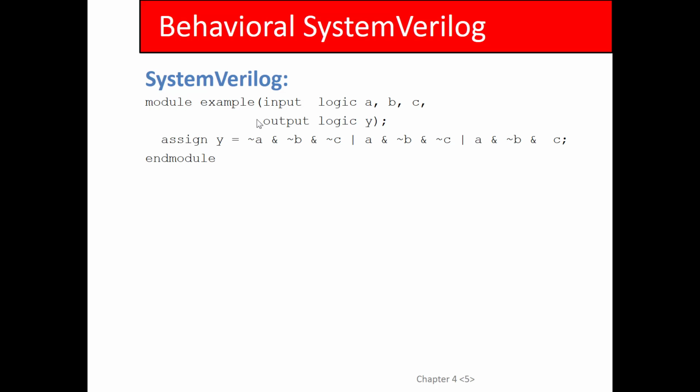The other thing you'll notice is this is a common convention in SystemVerilog. Notice that you say input logic A, B, C, and then you have output logic Y. It's like, okay, well, A is an input, I got that. Y is an output. But what are B and C? It's not clear, right? There's no label, there's no declaration for those.